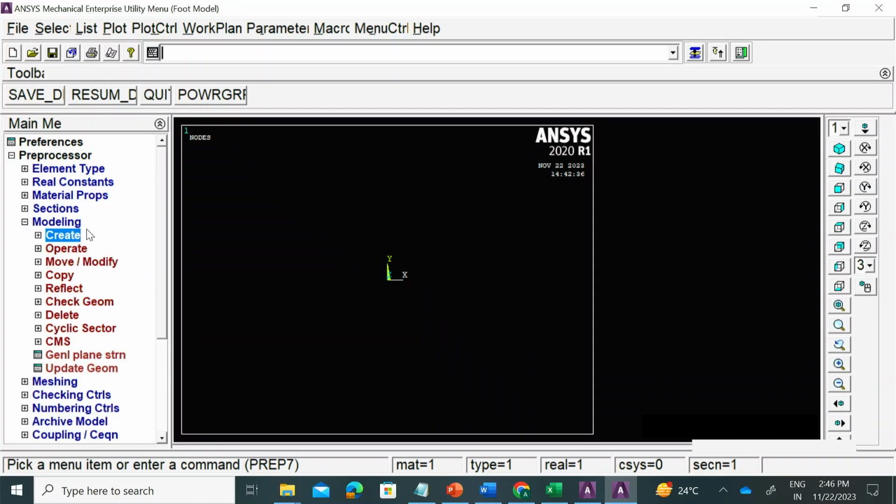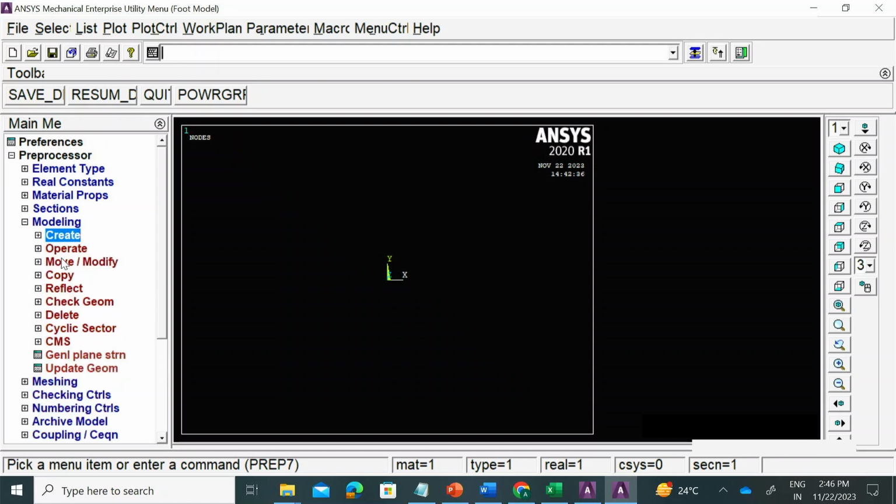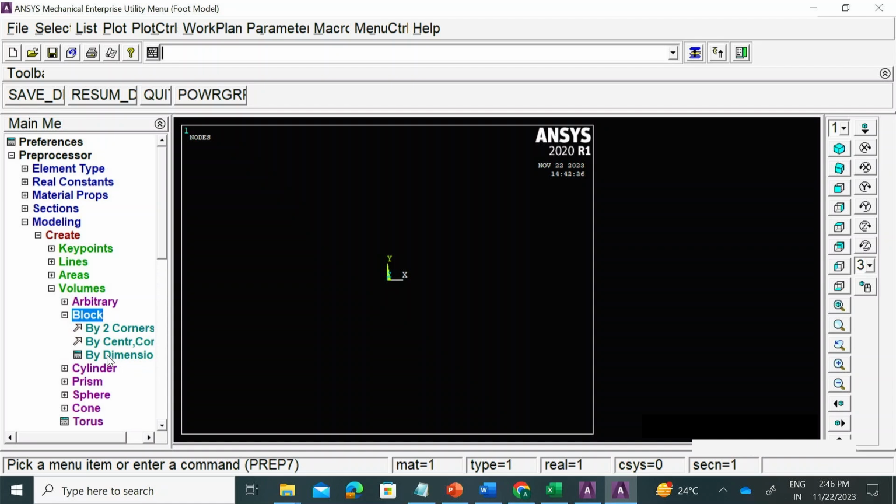So I'm going to use the bottoms up approach while I do that, right? Or what I could do is I could use the bottoms up approach and a mix of a standard method where I straight go to the model. So let's create a model first. I want to create a volume, and as we know, we can only create very regular volumes using this option, and bottoms up approach allows us to use different kinds of techniques through points and connections and creating areas and volumes to create much more complex geometries, right?